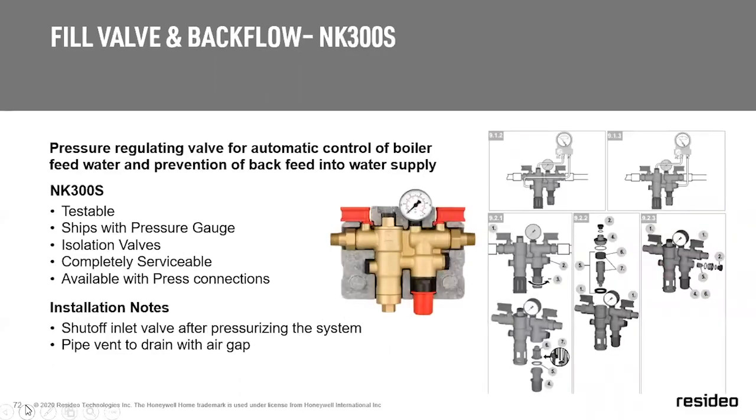And we also have a dual backflow, the NK300, which is probably going to be code in the future. A lot of municipalities are looking for redundant backflow protection, and it's completely serviceable. It's one casting, which is nice. It has service valves on it. And as you see, there's a styrofoam there. It actually can be sandwiched in that styrofoam if you're insulating the whole thing.